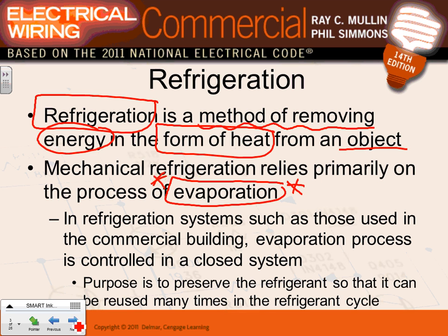The air is touching the pipe, and the pipe collects the heat and changes the refrigerant from a liquid into a gas. It gains heat, like boiling almost, right? Boiling the refrigerant into a gas. They use special types of refrigerants that can collect heat much better than water in this case. Okay, so that's your evaporator.